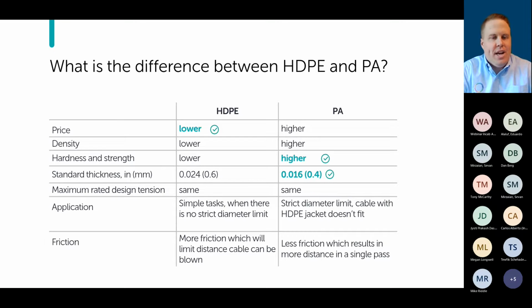Along the lines of looking at outside plant enclosures, if you can get your hands on a cable with an HDPE outer jacket and a PA jacket, I would definitely suggest that and have your guys work with it. Get their hands on it, and factor in the workability preference versus what you actually need from a functionality and design standpoint.